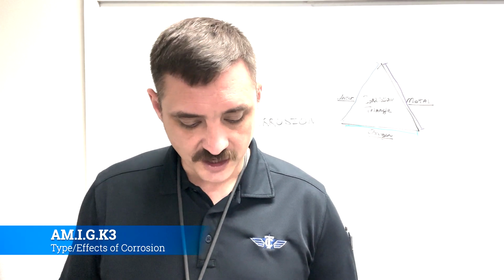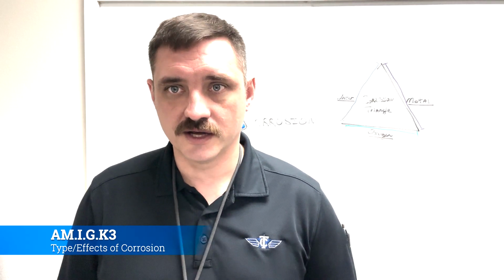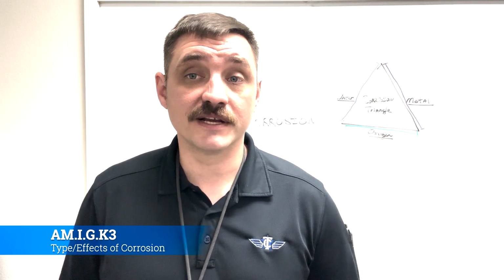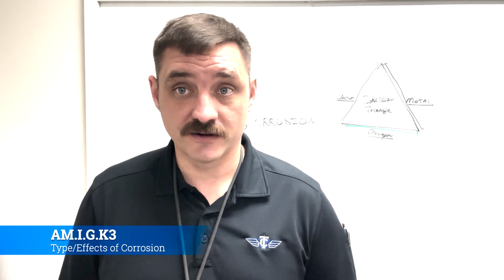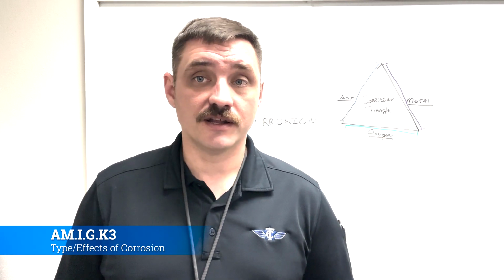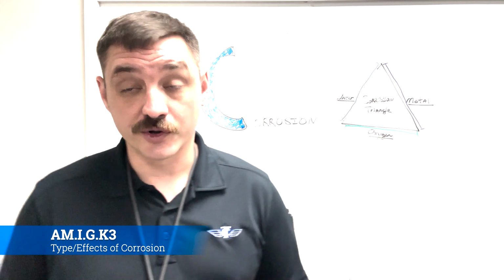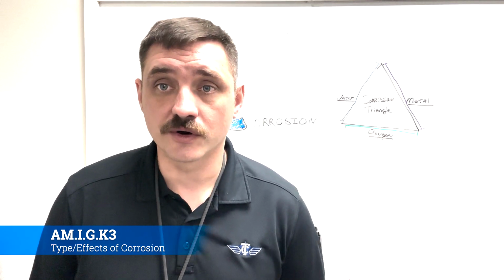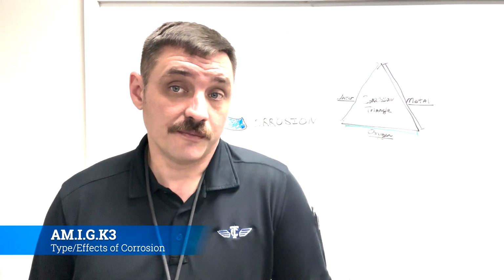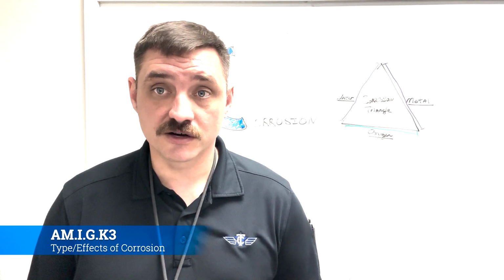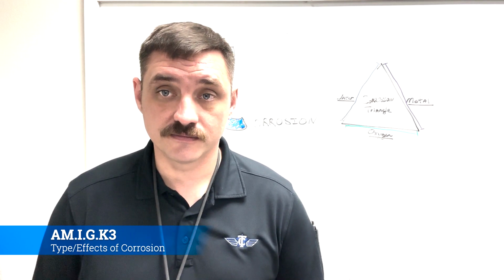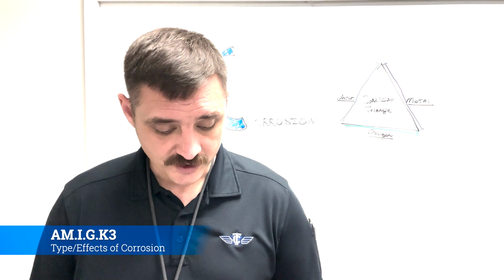Other ones, salts, obviously being next to salt water is a big deal. Being inside of big cities, they have a lot of smog. So if you flew into Beijing right now, you could have a corrosion issue if you're doing it on a regular basis, because that smog is going to absolutely eat up the airplane if left unchecked.